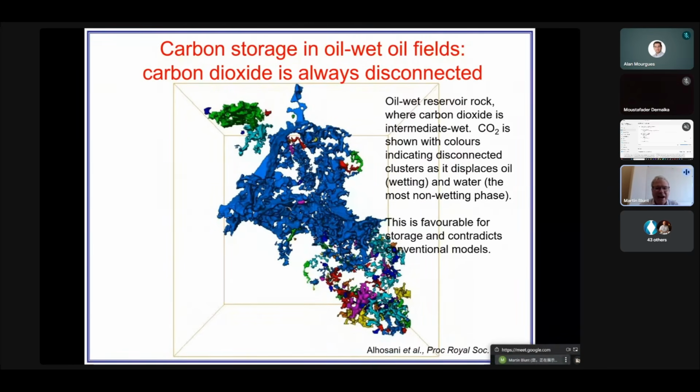However, every single empirical model that is used in reservoir engineering today assumes that gas is the non-wetting phase. It uses a gas rel perm that is measured just in the presence of mobile oil with irreducible water. And their gas is the most non-wetting phase. And yes, it moves through the biggest pores. And yes, it's connected. And yes, it has a high relative permeability. And you predict that a rapid breakthrough may be rather unfavorable performance. The reality is likely to be very different.